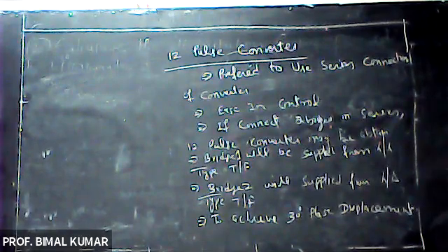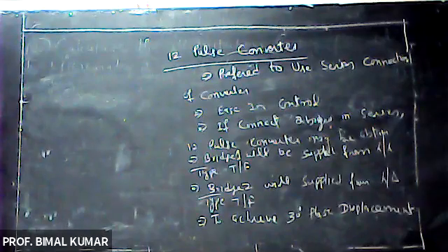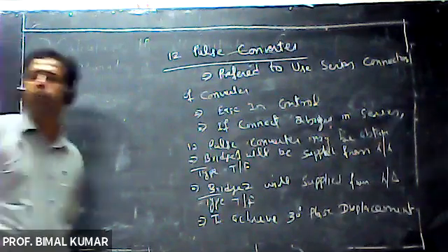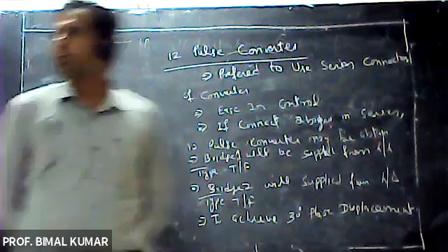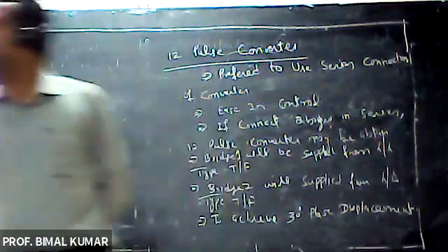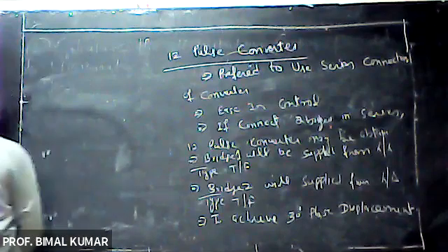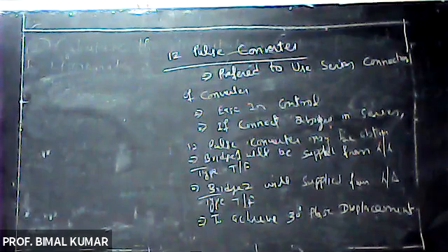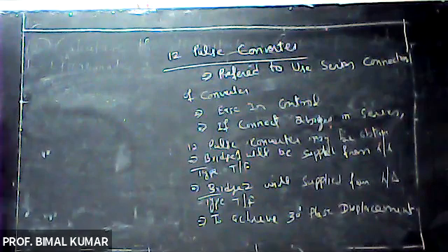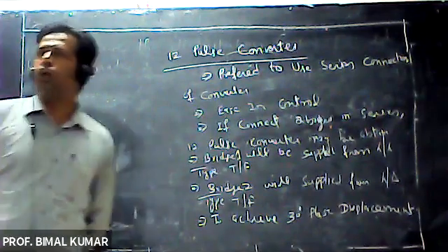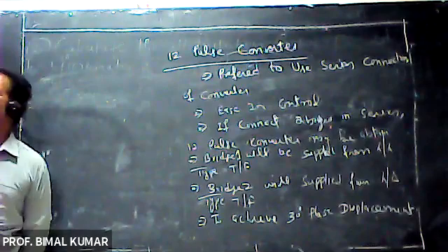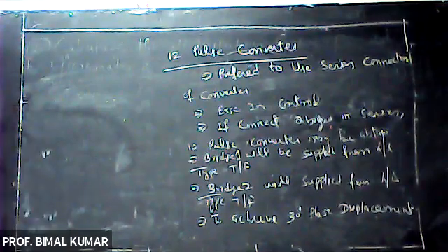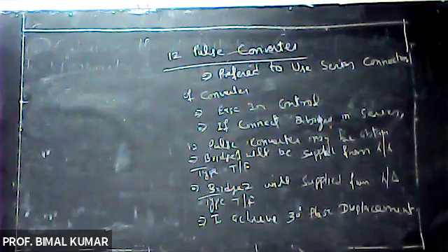If we are having 6 pulse converter, then in that cycle of the 360-degree, we are getting 6 pulses. And we will have to filter it out to get the smooth DC output, or to get that pure DC output, we will have to smoothen that output of the 6 pulse converter.